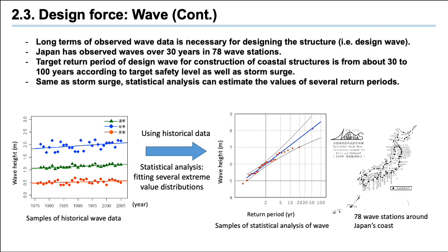The target return period of design wave for construction of coastal structures is from about 30 to 100 years according to the target safety level. Same as storm surge, statistical analysis can estimate the values of several return periods by using a series of annual maximum wave height.